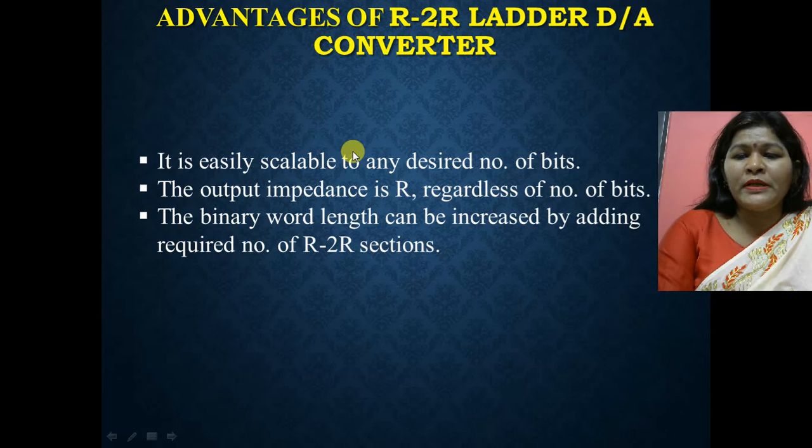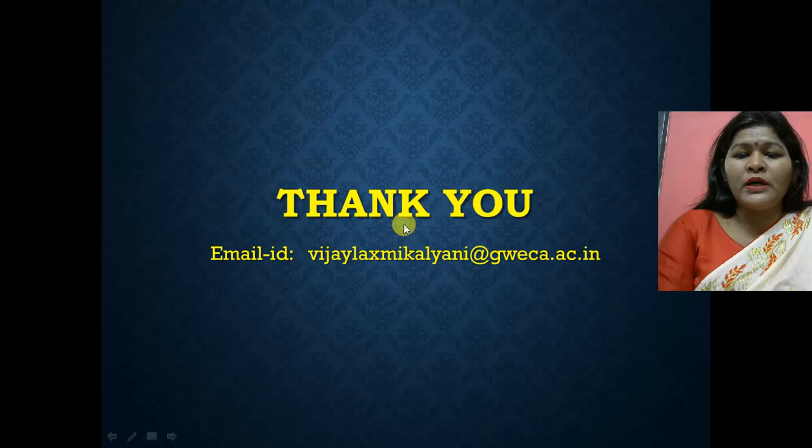This R-2R ladder D/A converter has many advantages. It is scalable to any desired number of bits. The output impedance is independent of the number of bits. The binary word length can be increased by adding the required number of R-2R sections.